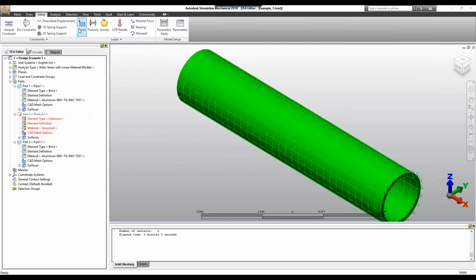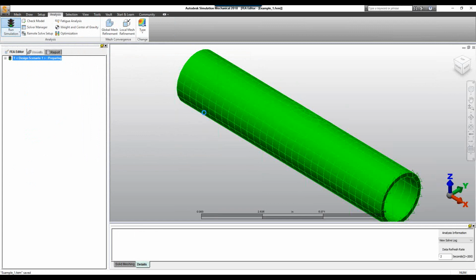And that's all you need to do. Go to analysis, and we would run the simulation. So Marwan, a short question, or probably a brief explanation for the attendees. In CFD, you run a pipe with a fluid inside it, where you define at the inlet a velocity or a mass flow rate, and then on the outlet a pressure equal to 0. Is that right? That's correct.